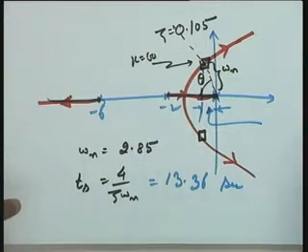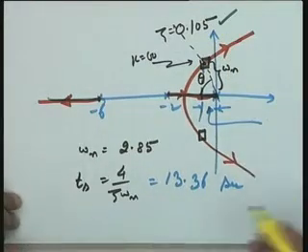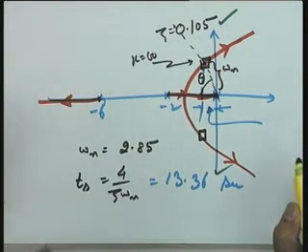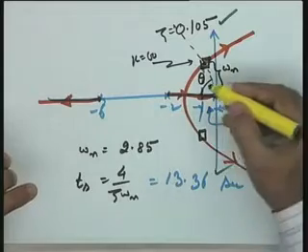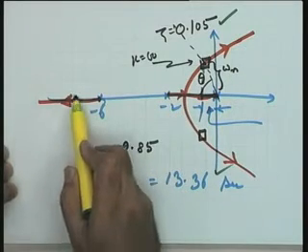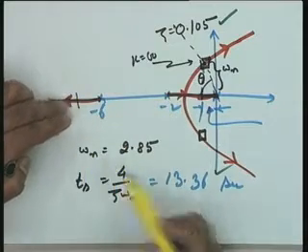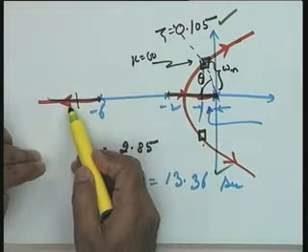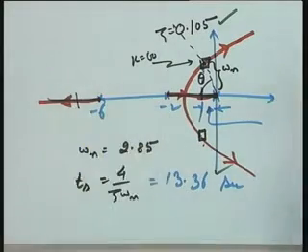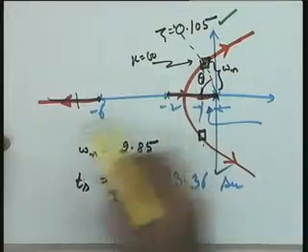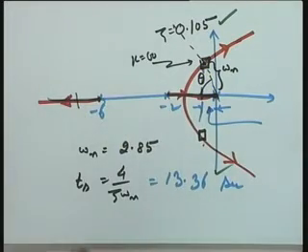Now, you see that the 0.105 and this particular settling time have meaning only when the dominance condition is satisfied. As I had mentioned in the tutorial class also, you need not check the dominance condition by taking a third pole over here, because after all this is going to be less than 1 and your pole has to be at a distance more than -6. So, the dominance condition is satisfied in this case, and therefore, you need not locate the third pole for the value of K equal to 60. In this particular case, you can save time.